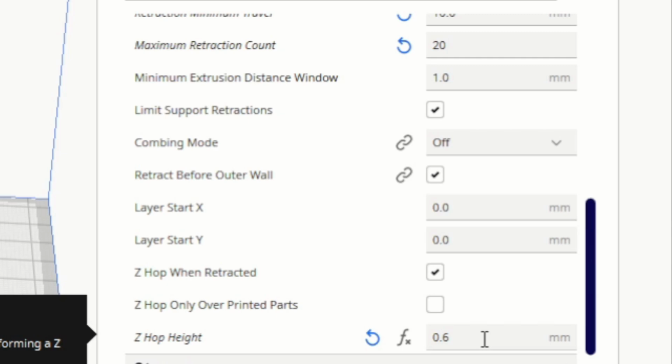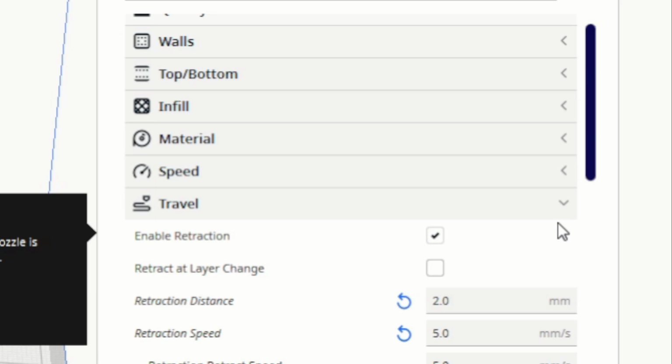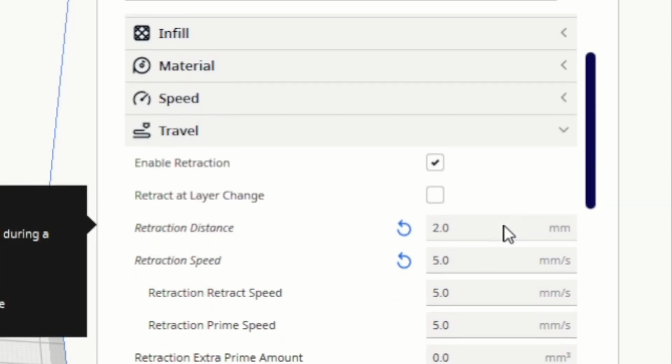This will vary a little bit, it really depends on the material you're working with. Now, if your 3D printer has its extruder be really aggressive, for example, my giant Core XY 3D printer, it's a Trudon. Its extruder is so aggressive that I cannot use PLA with it. I don't know if it's that particular extruder that they shipped out of the factory, but for some reason PLA will just grind to a halt, it'll start jamming up, so I have to only print PETG with that 3D printer. And even then, sometimes it has a problem with just shoving stuff out of the nozzle.